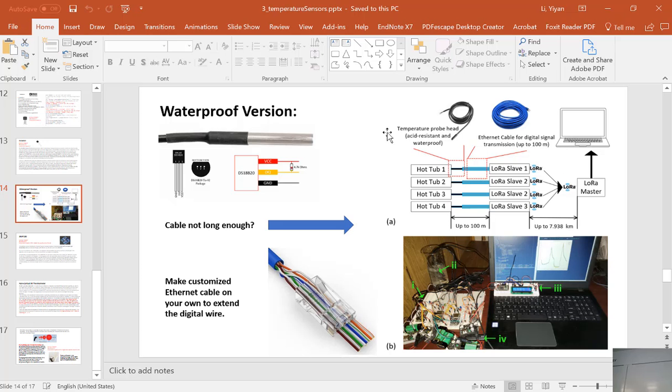All these caps along the transmission line are why the digital signal will decay or attenuate when sent over a long distance. So the problem is we won't be able to send the digital signal a long distance if you do not use a special cable.